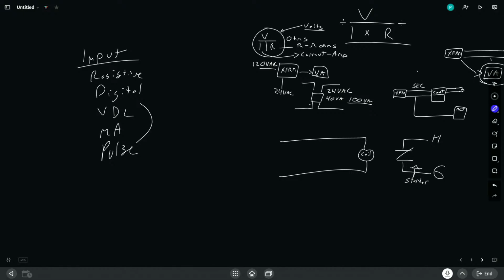So you have to interrupt the wire and actually put your leads in between one side of the wire to the other side of the wire to detect that current. On the output side, we have 3 primary outputs. We have voltage, which is either internally sourced or externally sourced. This is typically 24 volts AC, although it can be 120.